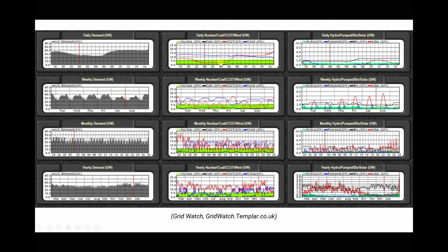However, we need to be able to meet those increased demands from 6 o'clock to 9 o'clock and throughout the working day. And what we see is that that's actually being provided by our combined cycle gas turbines. So when demand increases, more gas is consumed in order to meet that demand. Then as that demand decreases, the amount of gas once again is reduced and we're no longer producing as much electricity by the combustion of gas.